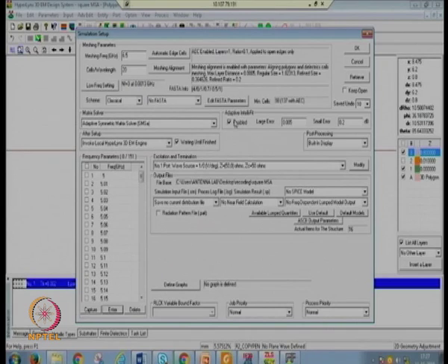One more thing I want to say, adaptive IntelliFit, it is given here. If you check this particular option, it will pick some frequency points from this particular range and then calculate the corresponding fields and then extrapolate your data and then show you the results. If you enable this option, it will give you good accuracy with relatively less time, but if you disable this option, then it will calculate at all the frequency points and your simulation time will increase. So, this is how you will proceed.